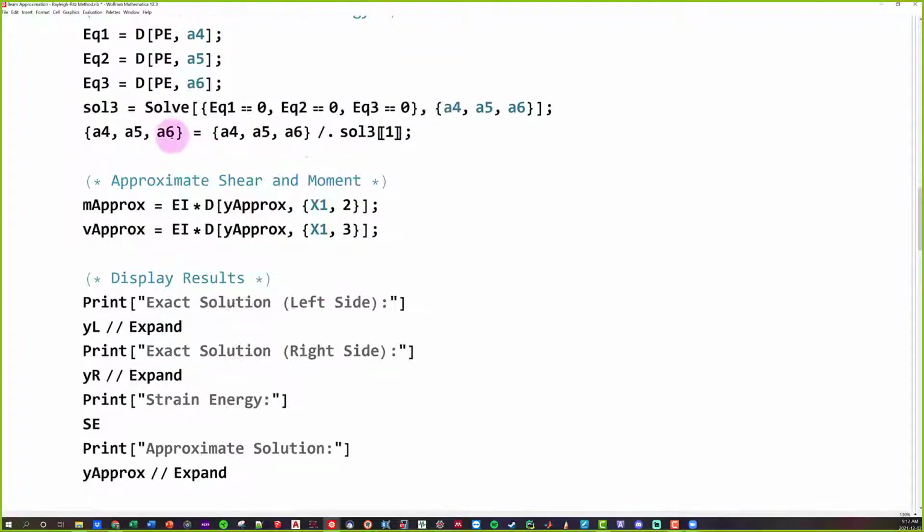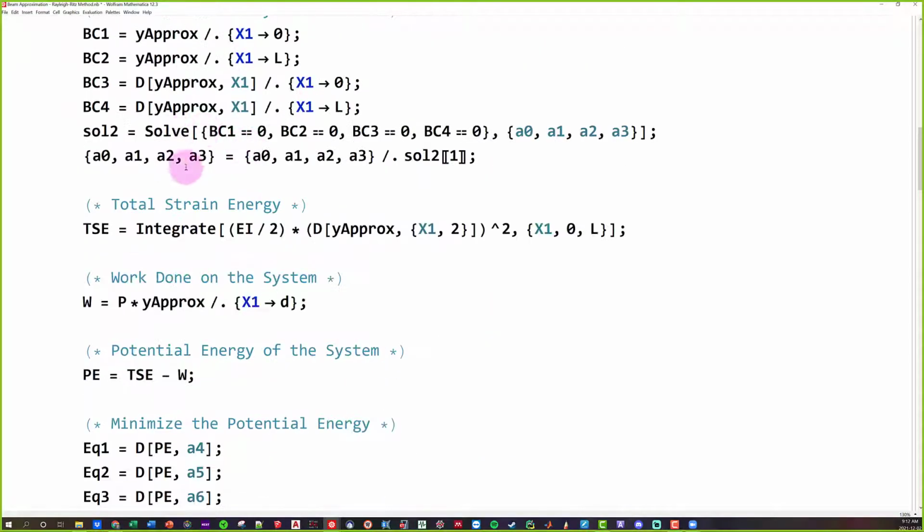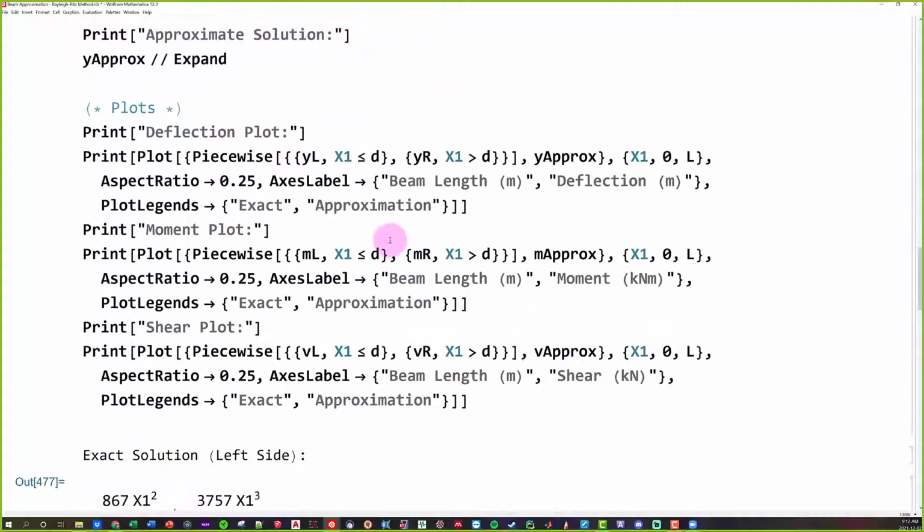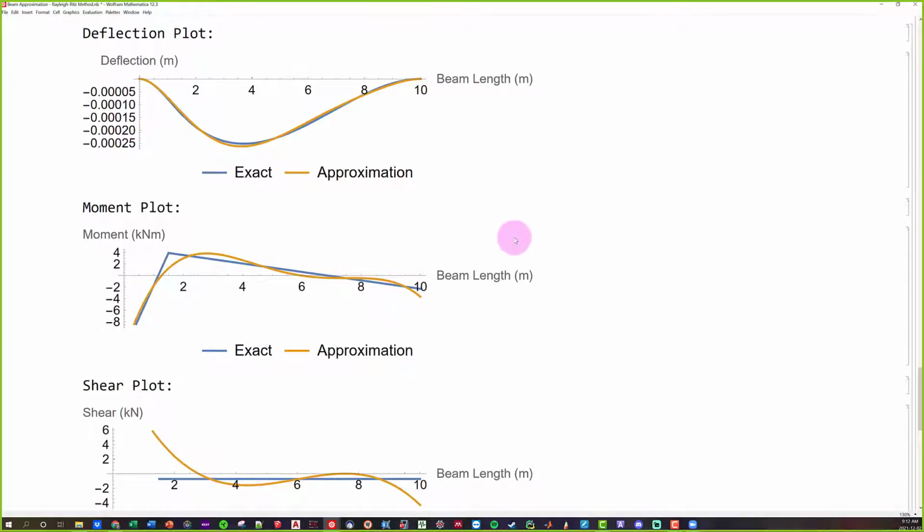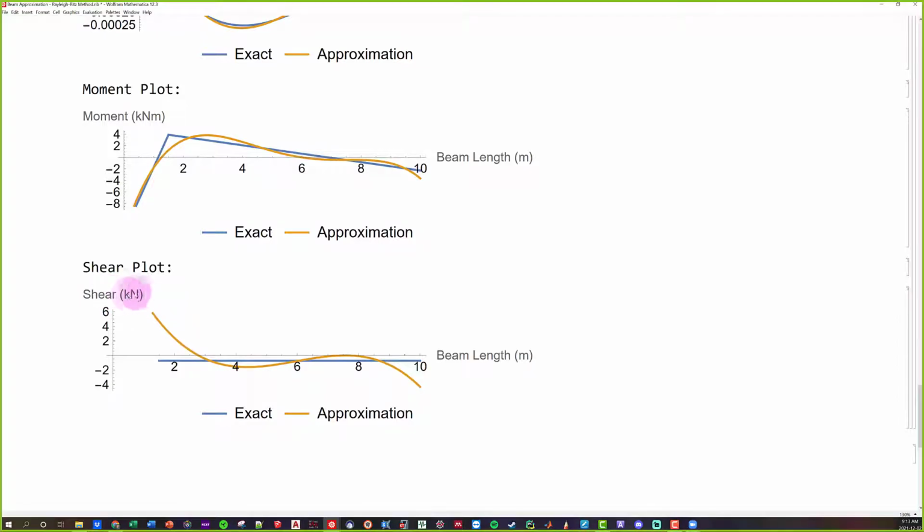Solution 1, I had it as solution 3, because we had solution 2 above and we had solution 1 even more above. So this is the last thing I want to leave you on when it comes to these approximation methods, because this is what happens a lot that you'll see in the finite element method. Deflection, really good. Moment, it's pretty good. Shear, remember there's a kind of a bar way up top here, and then the discontinuity, and then constant. Shear is kind of iffy.